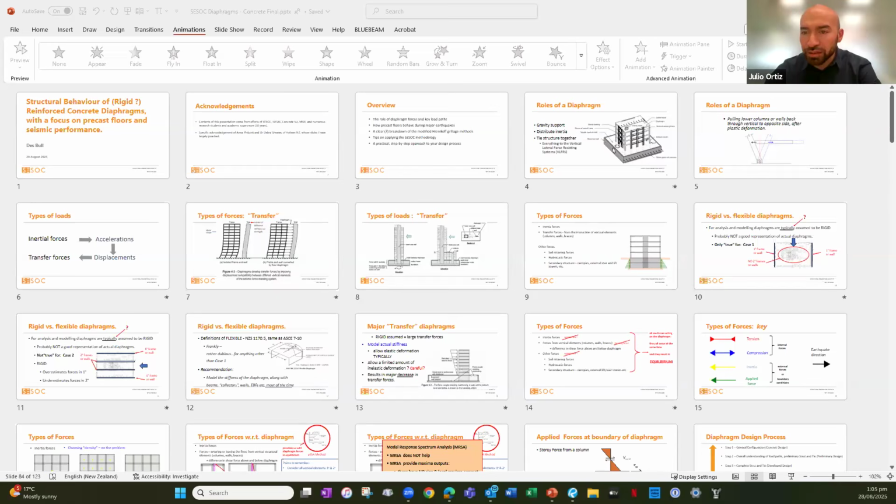All right, thanks, Des. Oh, by the way, the PT is put on as an external load. When we talk about the loads we put on the floor plates, if you're thinking about how to take into account the presence of the pre-compression, you'd put it on as an applied load on the diaphragm, and that will change the shape of your strut and tie solution. Yeah.